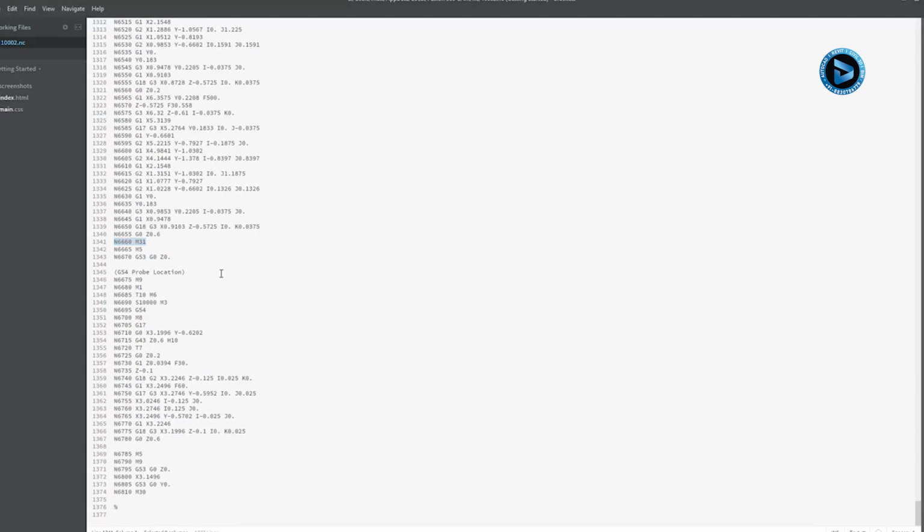Depending on the reference that you're looking at, M31 can potentially be called chip auger forward. It could also come up as an interlock setting. There are different ways that this gets posted out to different machines. So depending on the post configuration that we're using, we might see a slightly different variation of what code is included.